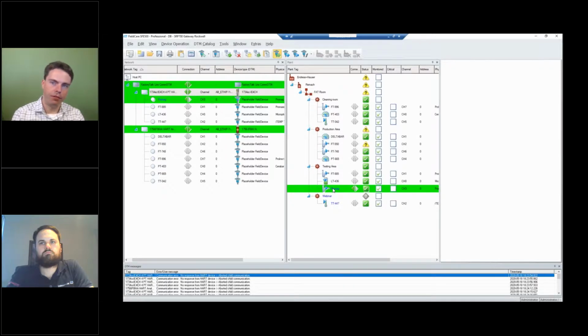So then we can put that in front and you can get access to that. That way, the system is also very versatile. So you can have one fits all. So let's say maybe you have legacy installations with the old Siemens and old Honeywell and some parts Yokogawa. Then you would have, first of all, to have HART cards in all the systems. And secondly, you would have 3 different systems. So you have a Siemens, a Honeywell, and Yokogawa system.